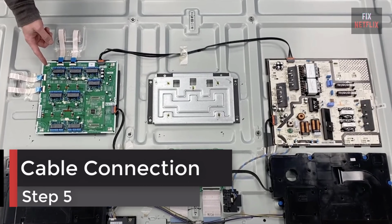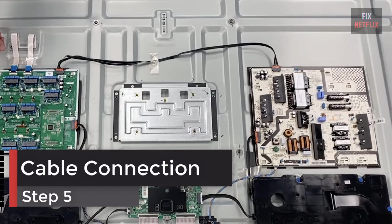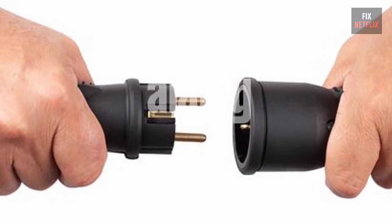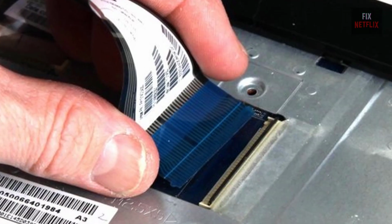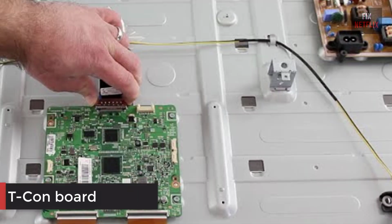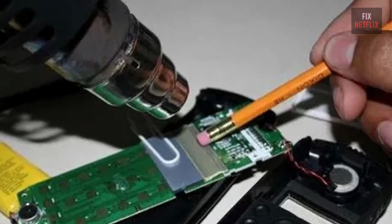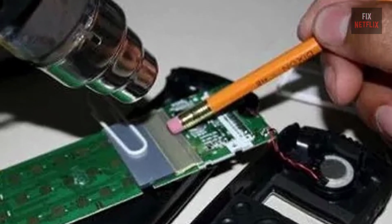Step 5. Cable connection. Even before you test the various boards, just disconnecting each cable and reconnecting it can sometimes fix the problem. Especially important in this step are the ribbon cables that run between a small board called the T-con board and the main board. You might even want to clean the contacts on the ribbon cables with a pencil eraser before reinserting them.